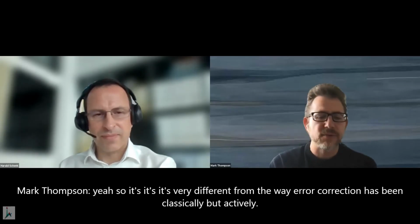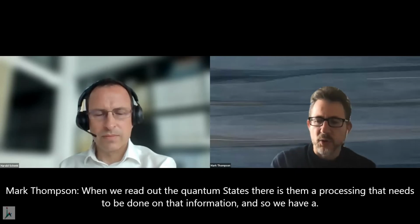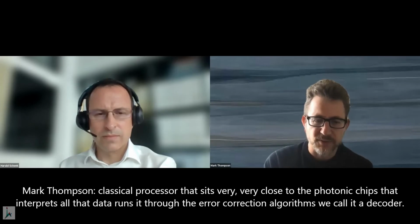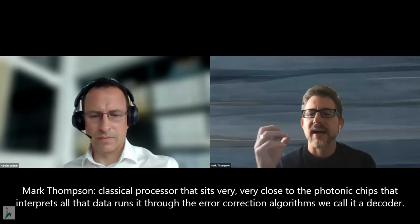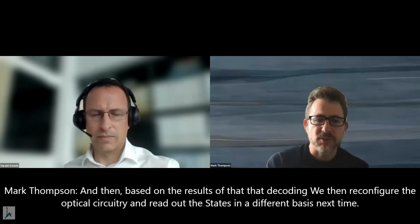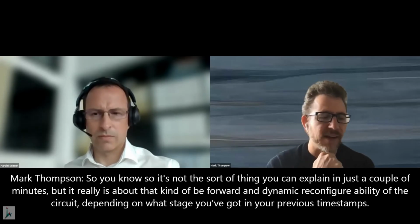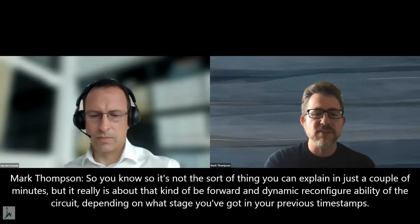It's very different from the way error correction is done classically, but effectively when we read out the quantum states, there is a processing that needs to be done on that information. We have a classical processor that sits very close to the photonic chips that interprets all that data and runs it through the error correction algorithms. We call it a decoder. Based on the results of that decoding, we then reconfigure the optical circuitry and read out the states in a different basis next time. It's not something you can explain in just a couple of minutes, but it really is about that feed forward and dynamic reconfigurability of the circuit depending on what states you got in your previous time steps.